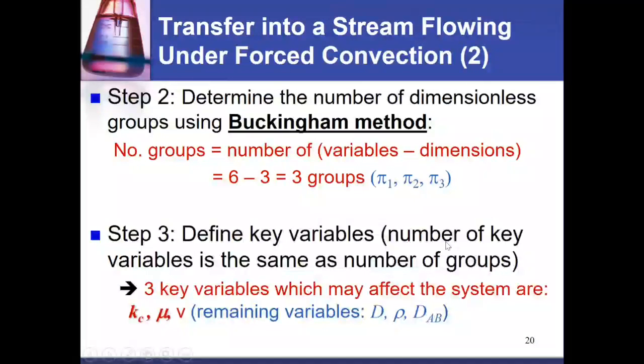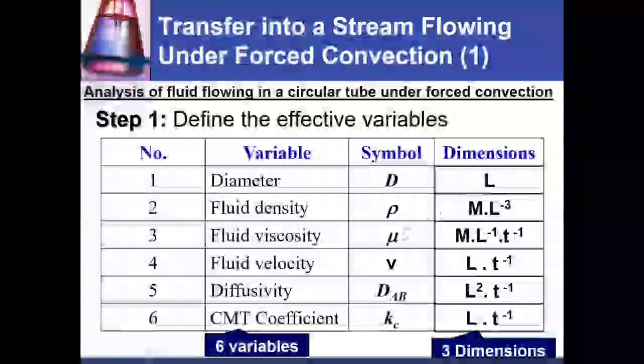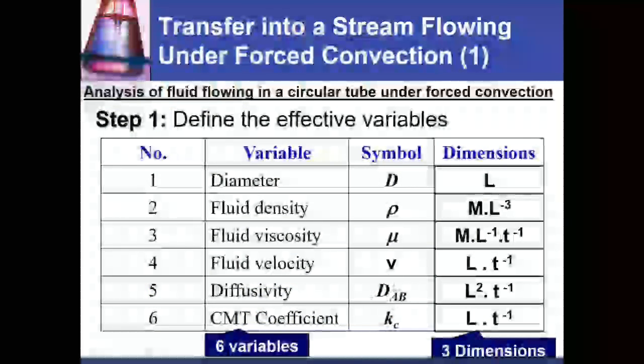Yes, Hatim. Doctor, what about temperature and pressure? They are captured here in the density and the viscosity, and also in DAB. Because density is a function of temperature, viscosity is a function of temperature, and if you have a gas, density is also a function of pressure, and DAB is a function of pressure if you have a gas. So they are captured there indirectly.